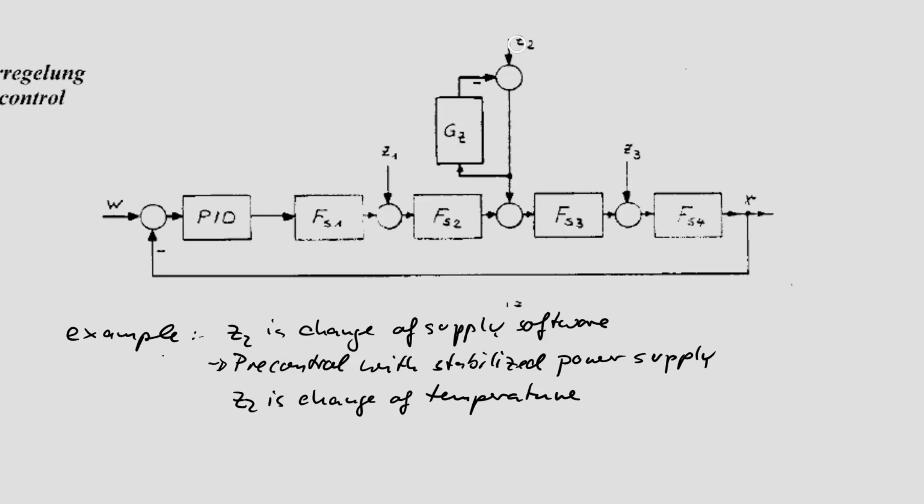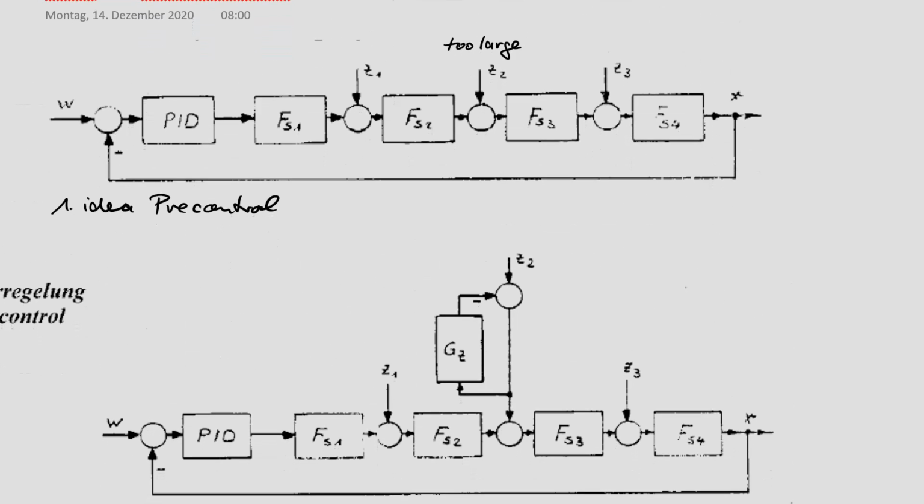Now the ambient temperature can influence system behavior in many applications. For example, if you have a sinusoidal generator, then the temperature changes the base frequency of the quartz. Or if you have a sensor principle, then you need a sensor, and many sensors also have a rather big temperature dependence. So it could be a good idea to isolate the ambient temperature from your system.